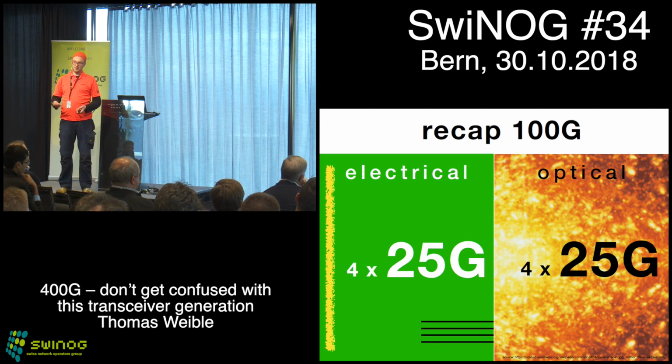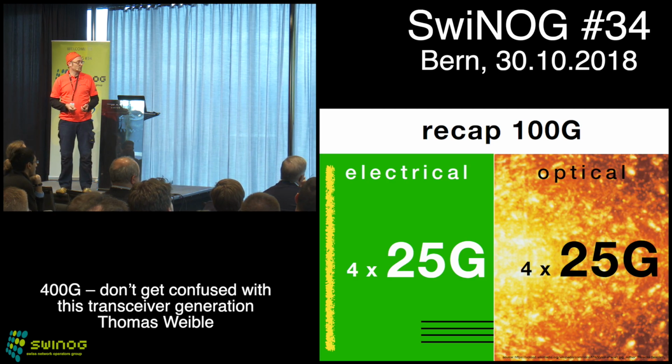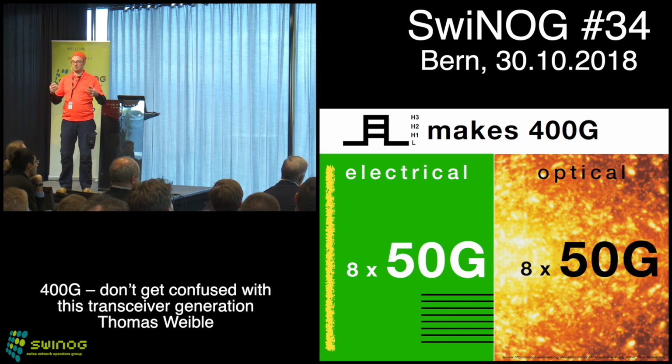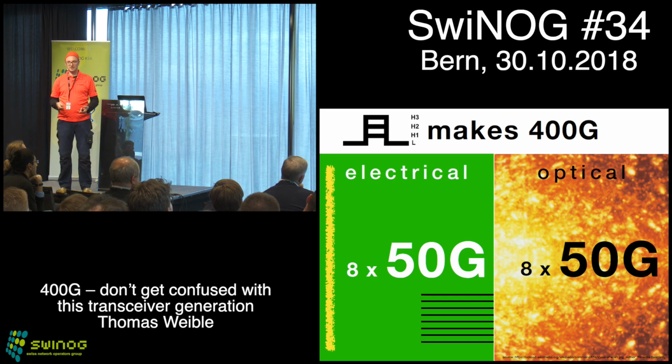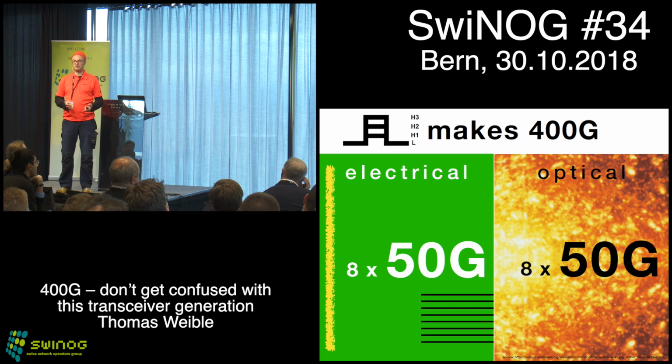Now for the upcoming 400 gigabit, there will be 2 generations. The first one will look a little bit different, and here you can see where the second doubling is coming from: we increased the amount of lanes. From our host, we get 8 lanes now running at 50 gigabit. On the frequency side, we're still at 25 gigahertz, but we got PAM4 modulation there.